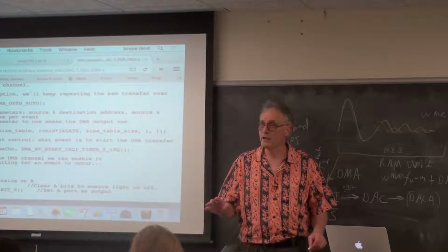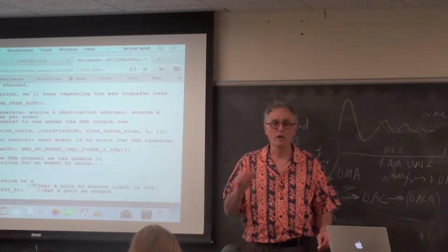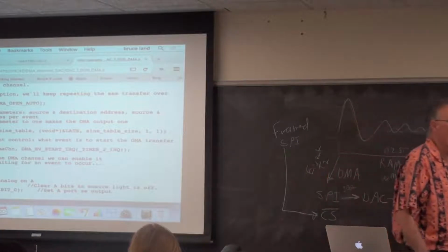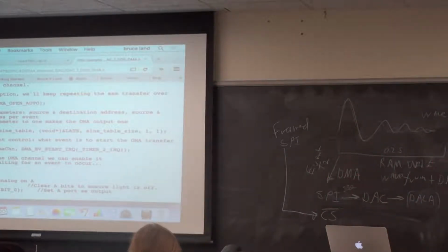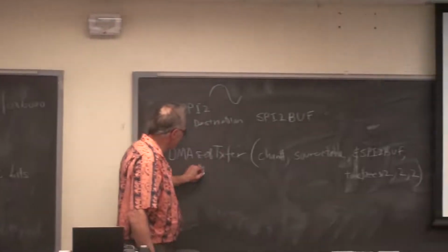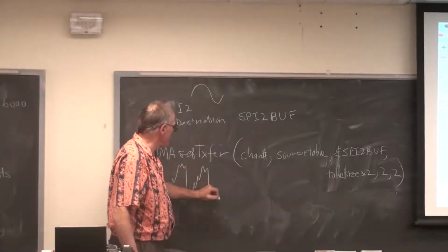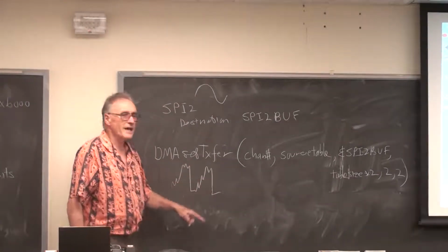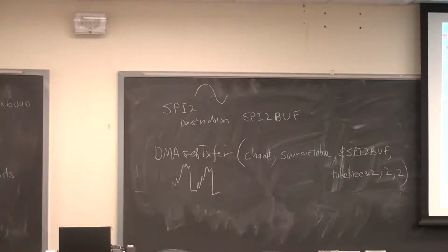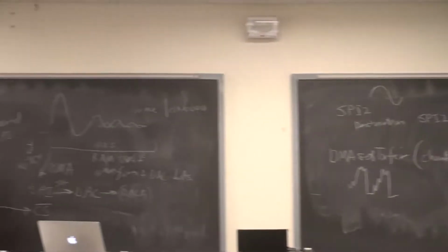On the other hand, if you want to make the table small and make the table be some repetitive function, like a sine wave. I mean, right now you have one cycle of a sine wave that you're sending. But maybe you could do something like this. Some nasty looking thing, sawtooth, store one cycle of that, send it out multiple times until you turn off the channel with an abort channel command.